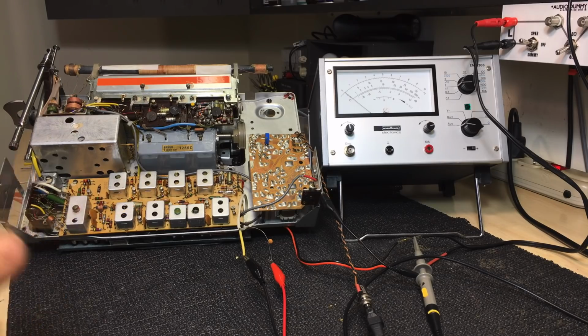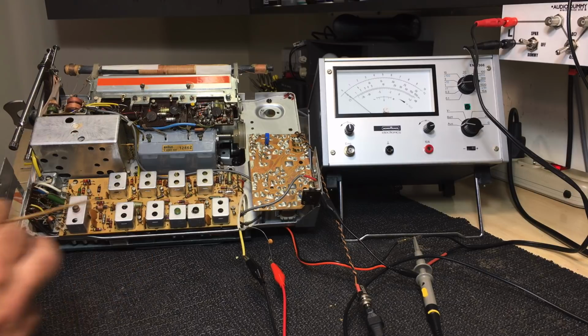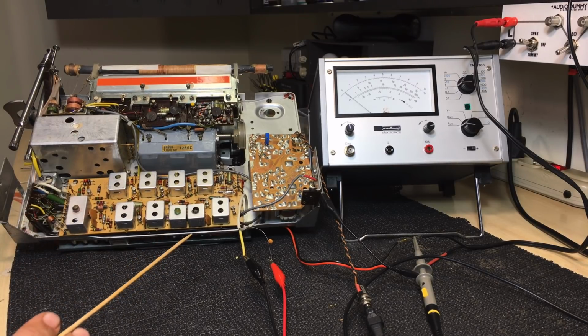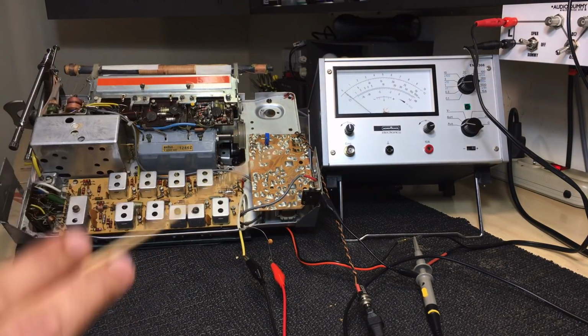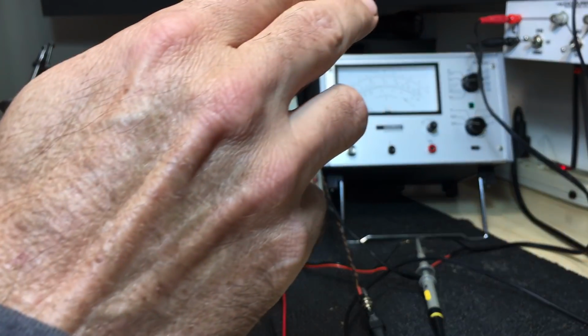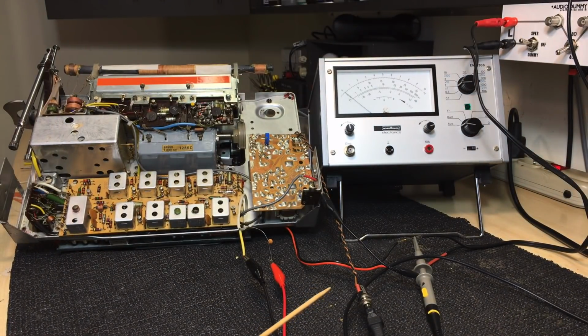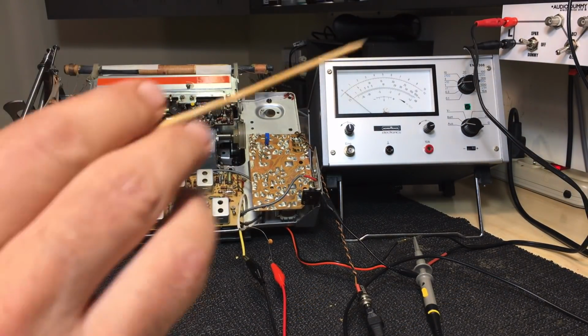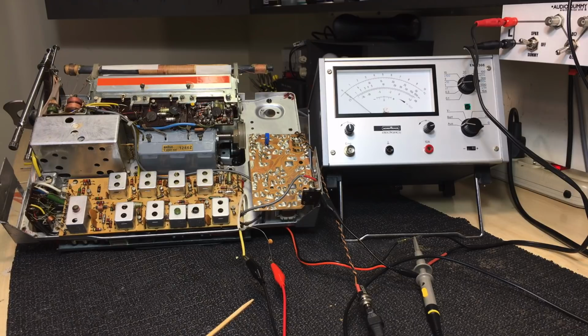That is a problem because I don't have a wobulator, and these levels of signals on this particular radio are not conducive to using the oscilloscope method, which is the same as a wobulator. All I do is I take the trigger out signal from the signal generator, and you can put that into one of the scope inputs, trigger it with that one, and I've done this before. I won't go into all that. The alternative is to use a signal generator, not a wobulator and not a scope.